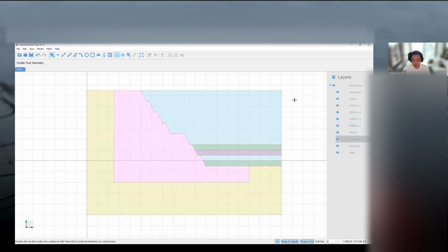The next thing we need to do is to define our boundary conditions. So these are the nodes that we'll be assigning boundary conditions to. So since this is a near surface model, this top surface is actually a free surface, so there is no boundary condition on the top. The left and right edges of the model will be assigned a vertical roller boundary condition.